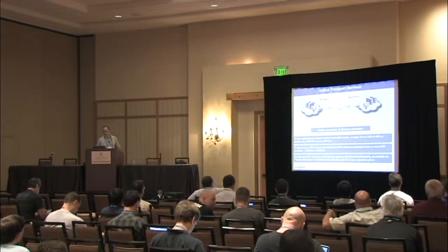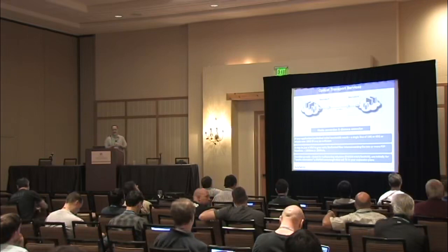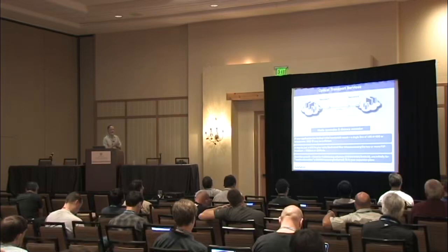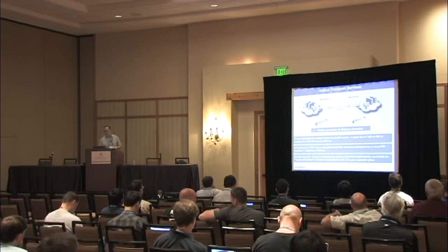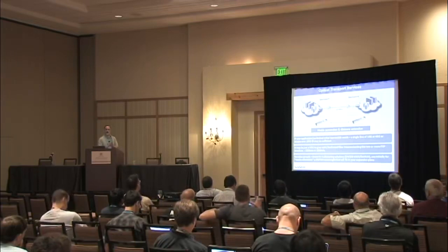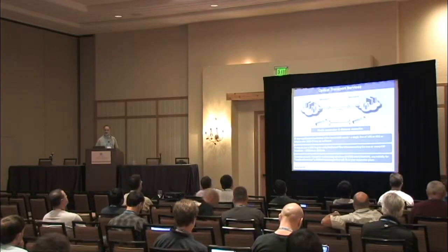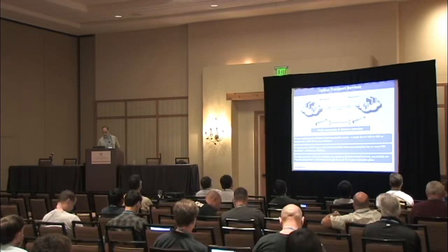So let's look at the simplest optical transport service, the media conversion and distance extension. With today's bandwidth of 10 gig or 40 gig, one line may be quite enough. Maybe just a multimode to gray optic, with a dedicated fiber interconnecting the two sides. And that's about it. Now, think about your future and invest in multiplexing elements and use one of the wavelengths as media conversion, as your single mode transceiver, because you may want to expand your network in the future. By doing this, you're not going to disturb the existing infrastructure.